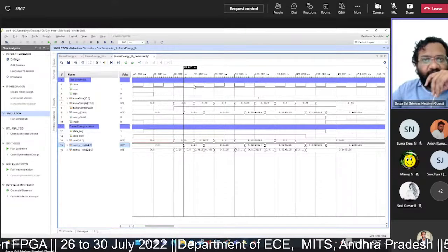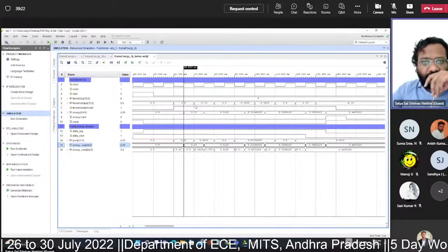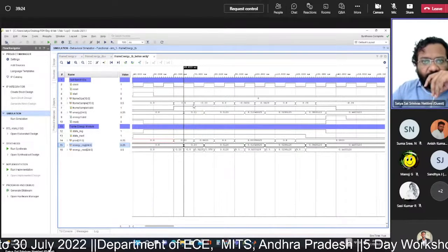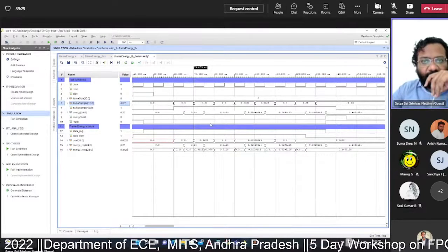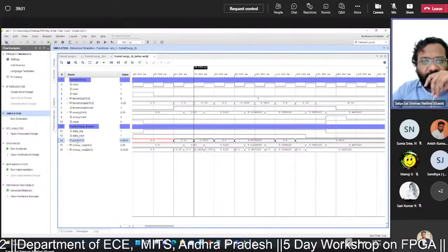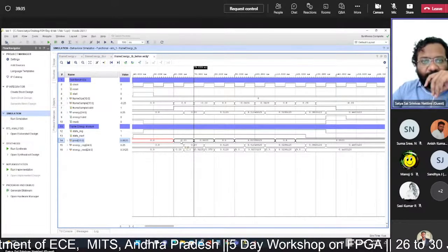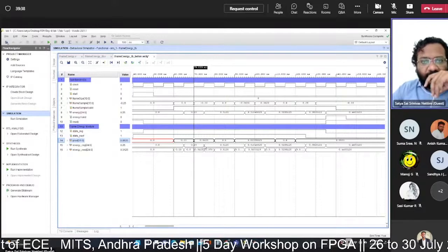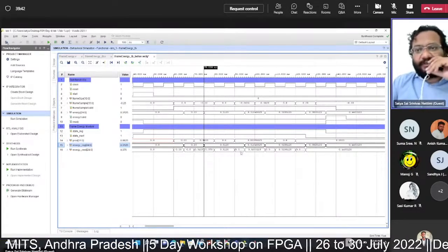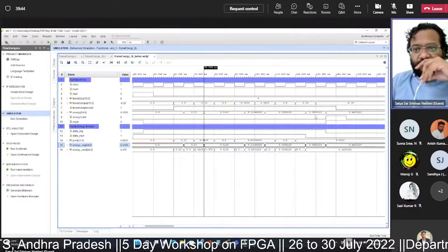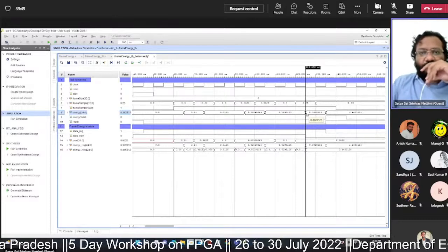Soon after, you gave a new sample, that is minus 0.25. The square of 0.25 is 0.0625. This value is now added to the existing value 0.25 in the register. That becomes 0.3125, and so on and so forth. This process will proceed till the count value.